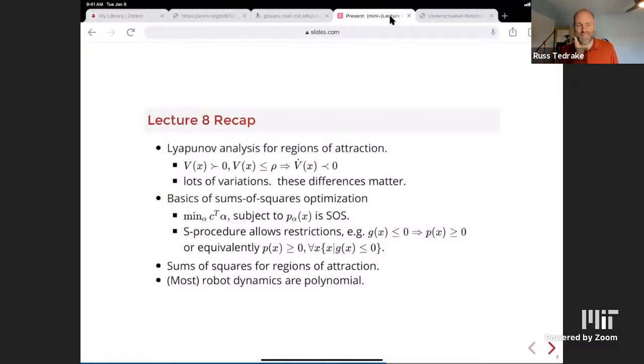Quick question. In the notes you talk about how the cost function from LQR is a candidate Lyapunov function, which surprised me a little bit. But then I suppose it makes sense, because the cost to go should be decreasing as you approach some goal state. When is it not just usable as a Lyapunov function?